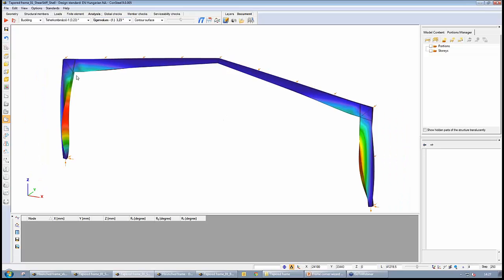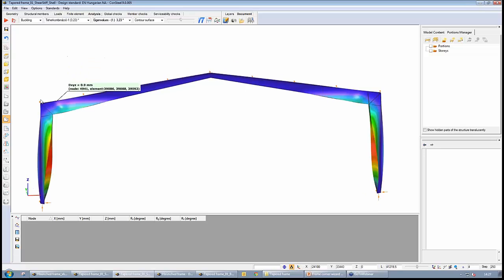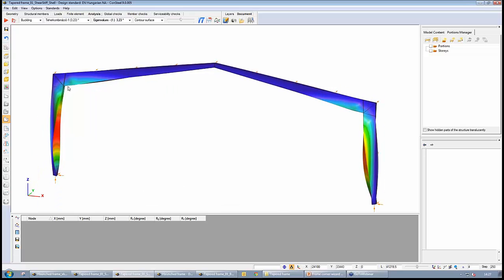So this shear stiffener not only affects the local buckling, but the global buckling as well, because it makes this frame corner zone even stiffer. This is very important, that of course the global behavior depends on the frame corner configuration. What is exactly the frame corner connection?